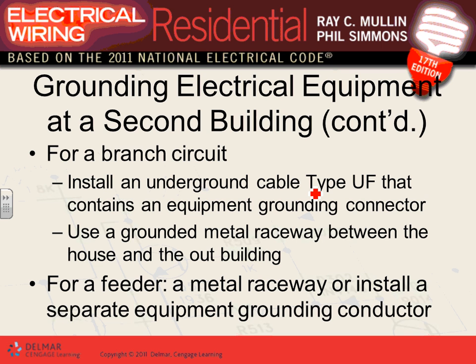So if it's a branch circuit, multi-wire branch circuits, you don't have to do grounding. Only if it's a feeder. That rule that I just talked to you about applies if you're taking a feeder. If it's just one branch circuit, you don't have to do that.